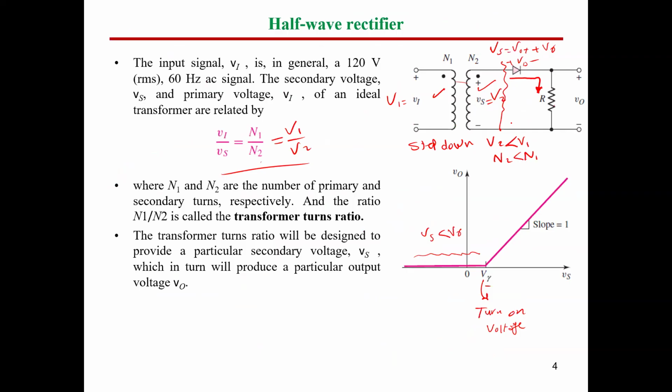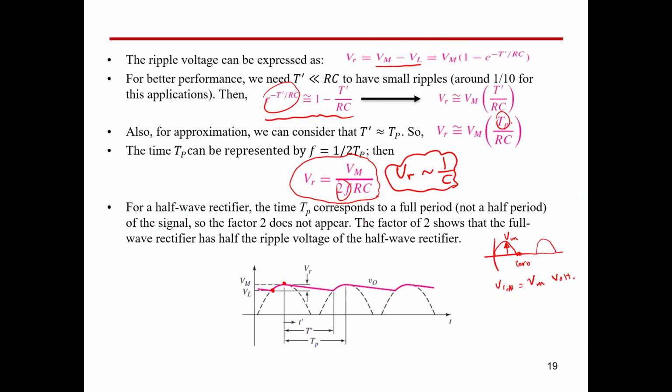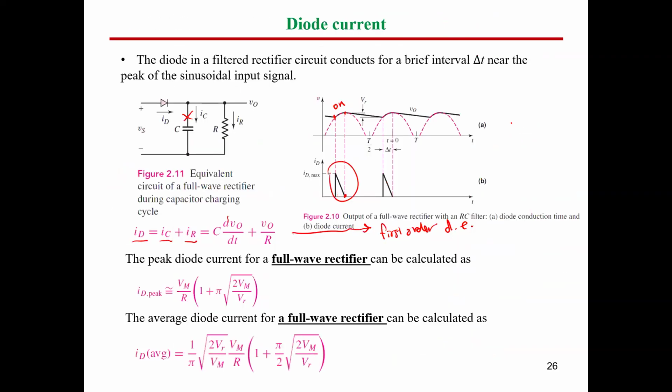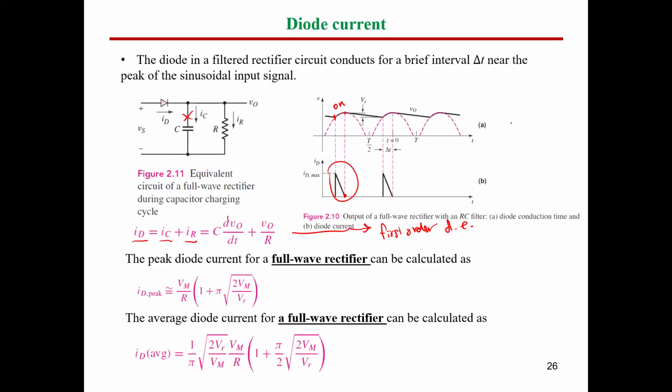So in our circuit, let's go back again. What will happen if your capacitor is broken, or due to any problem it's not working anymore in the circuit? In this case, this is going to be an open circuit, and the diode current will be the same as your load current. So in the design, guys, you have to consider the worst case scenario.